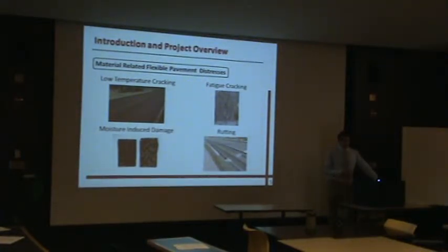What is the problem of RAP and of stiffening the material? Material which is stiffer will tend to crack faster. So low temperature cracking and fatigue cracking will be a big issue. Also moisture damage. This is a moisture damaged pavement, and this is the new pavement. So those 3 points are very significant when we talk about RAP and stiffer material. However, rutting is not very significant here because stiffer material tends to resist rutting more. Also, this project was especially for the northeast of the US, and the northeast is a colder region, as you know, and rutting is more susceptible in